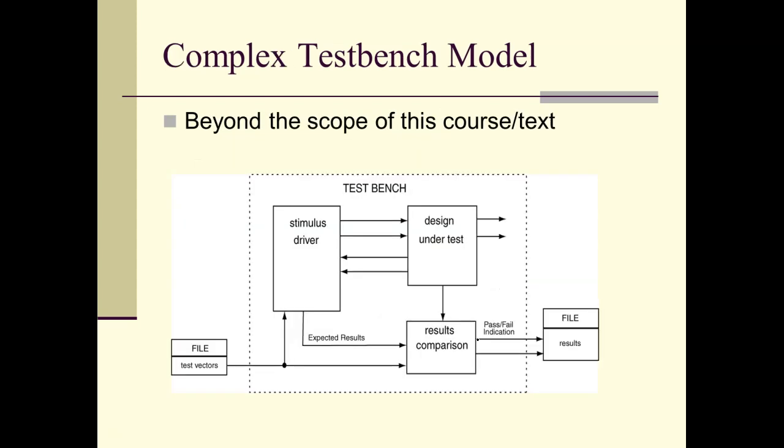So this is a really complicated test bench structure, which you'll run into in real life. It still has a stimulus driver and a device under test, and most of it's the same, but you can do a couple of different things. You can read test vectors from the outside world. The stimulus driver can do stuff with those in a control manner, and I could read expected results from a file also and make a comparison.